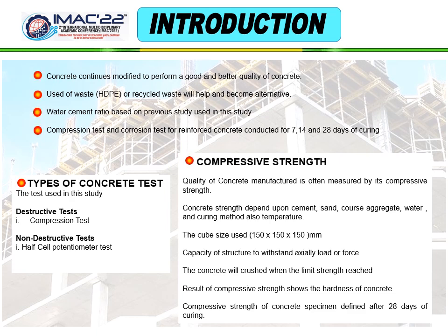The tests carried out in this study are compression test and corrosion test using Half Cell 2000. Compression strength test is used to know the quality of concrete.